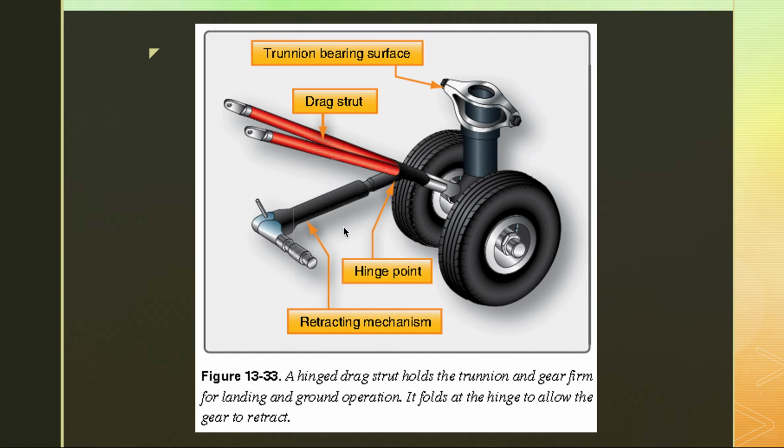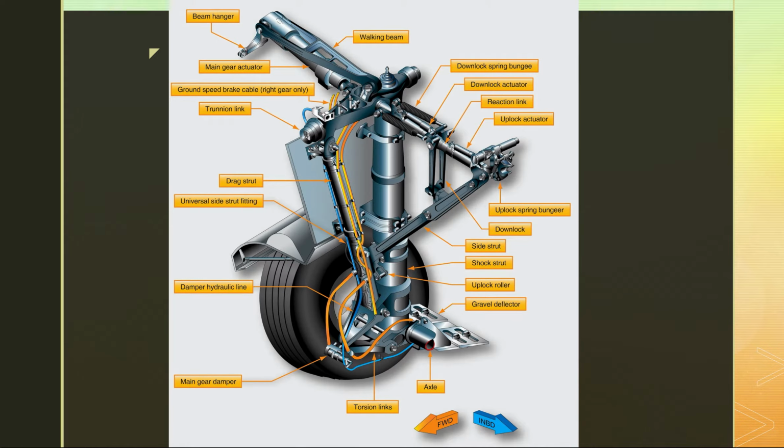We'll get into that. Here's a wheel that folds inward, usually, not always, but inward, and folds up into the fuselage or the wing. We have landing gear doors on the outside of this one, so those gear doors come up and down. We saw that in the 737 earlier. And we've got a lot of the same nomenclature. You see this includes some brake lines on there, the axle that the wheel goes onto. You got your brakes down there. This is a shock strut.